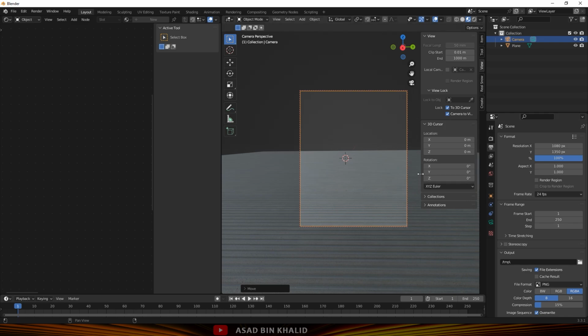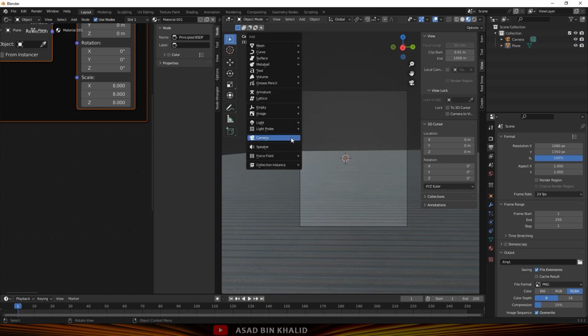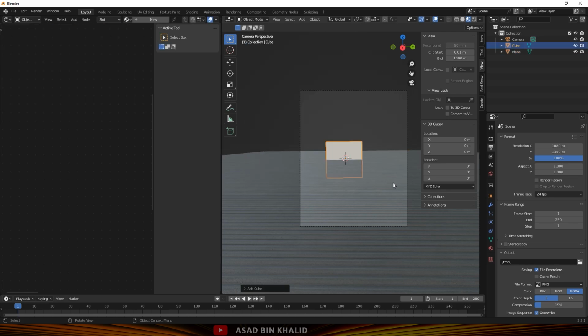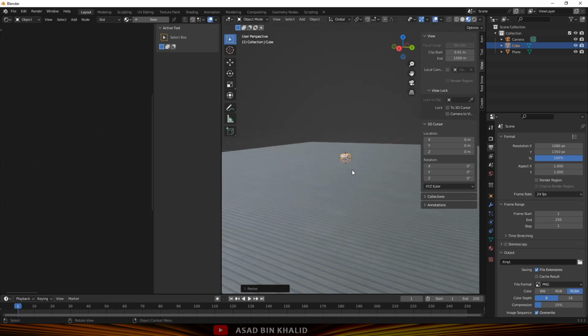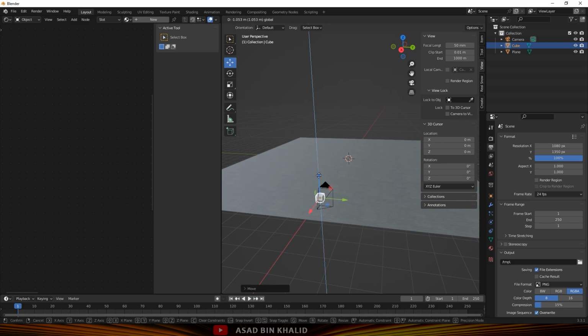So the next step is to create some kind of cube and build our scene. Again, I will unbox this. One mistake I made when I scaled up: I have to apply the scale. It's not a big deal, but make sure the texture fits right. But anyway, let's do it right now. Press Shift A, go to Mesh, Cube, and press S to scale it down. Excuse me, guys. Press the move tool, select it, and there we go. I put it like a foreground kind of thing, so make sure it sits down as well.